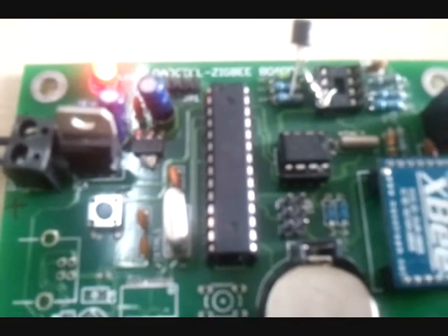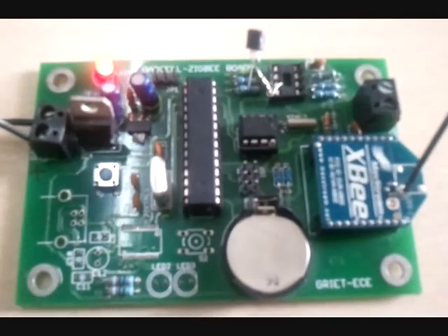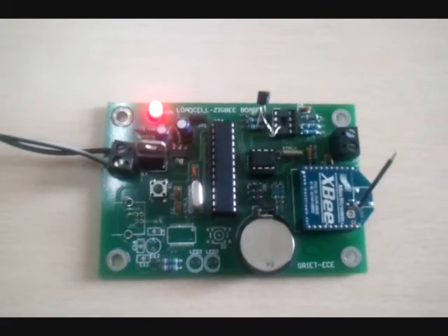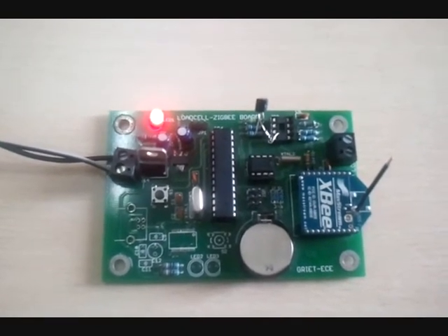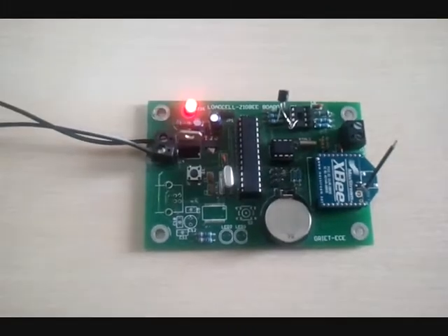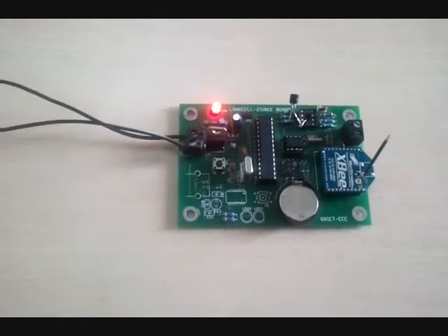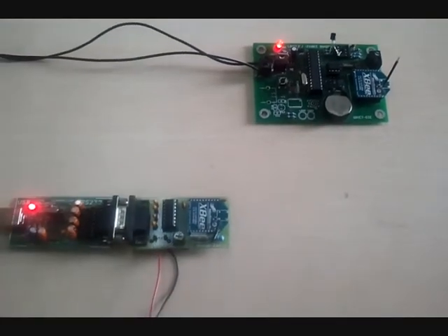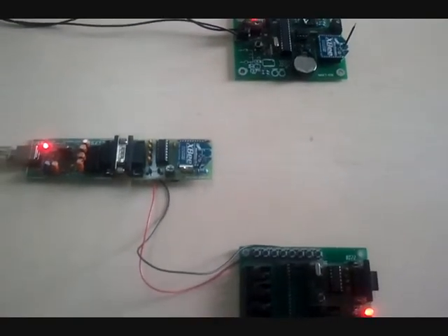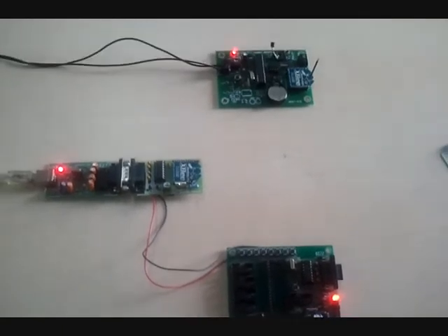The operating frequency of ATmega8 is 8 MHz. It has an internal analog to digital converter. The advantage of in-system programmer is we don't have to use an external bootloader. The initialization of ADC involves 3 steps: setting the reference voltage, setting the prescaler value, and enabling the ADC.